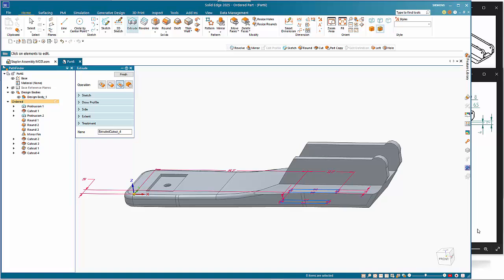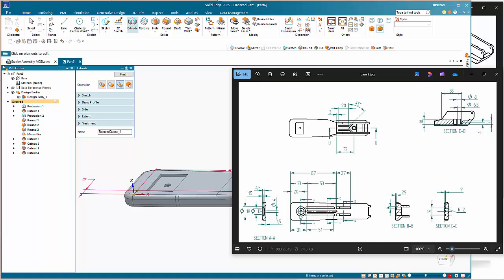So then we've got these 3 slots in here, which, as I said, 2mm deep, 2mm radius, and they're different lengths. So I'm going to use the slot command on this. You've got 31 by 51, and about the centre line is 7mm, 14mm. So 31, 51.